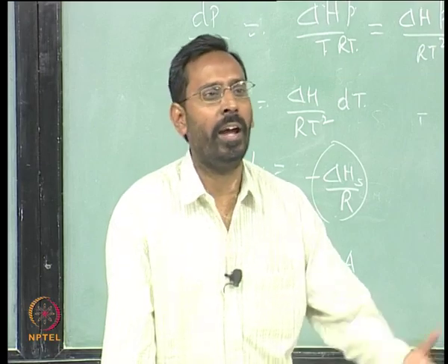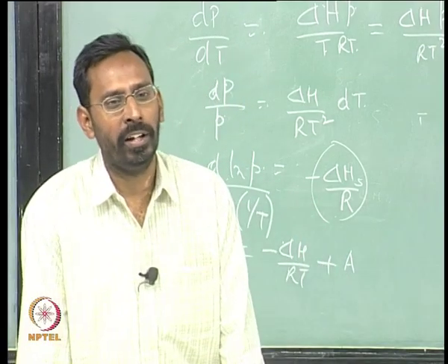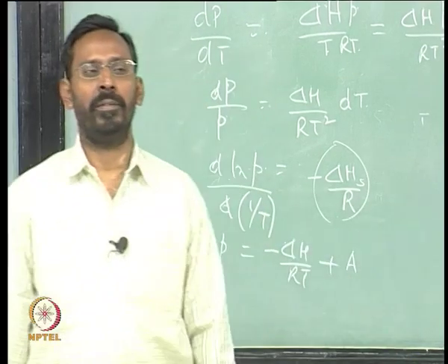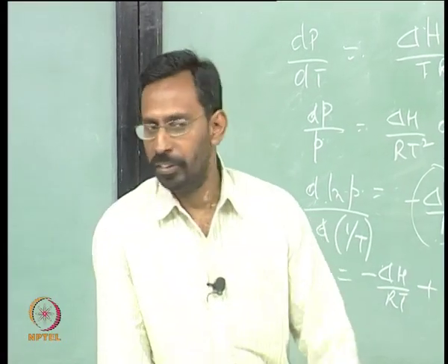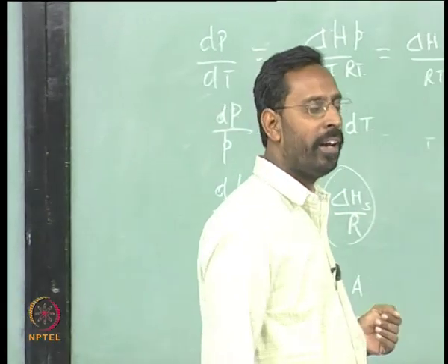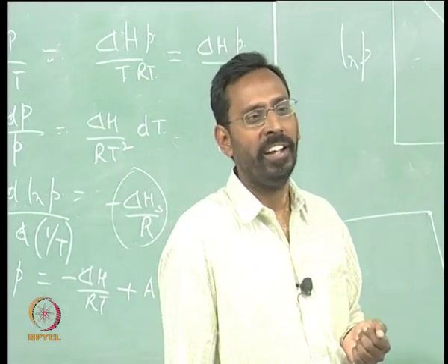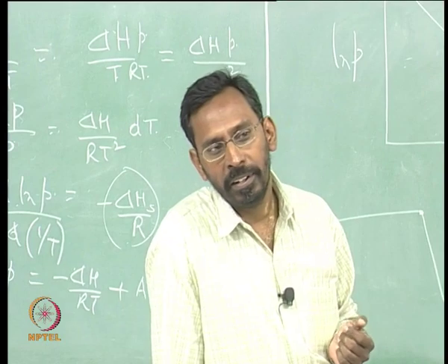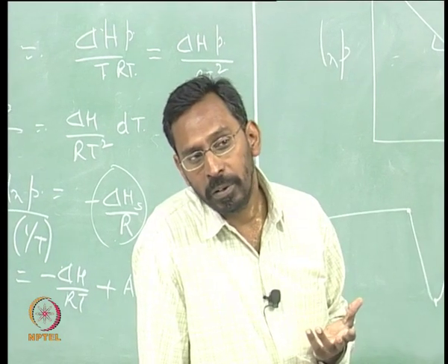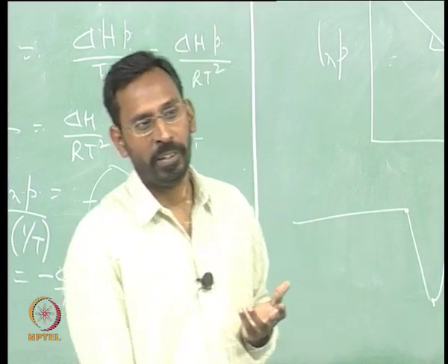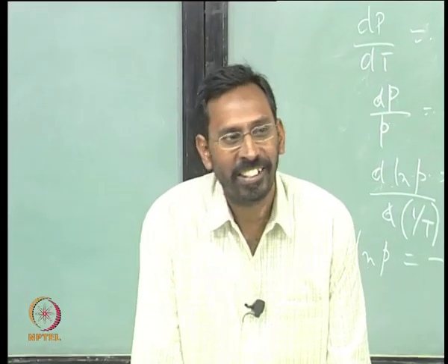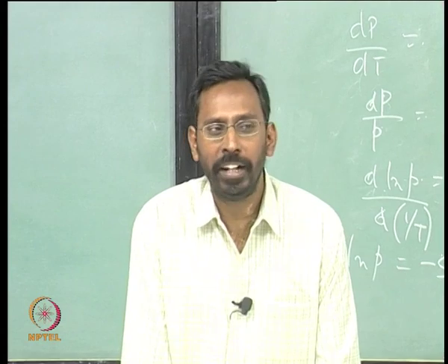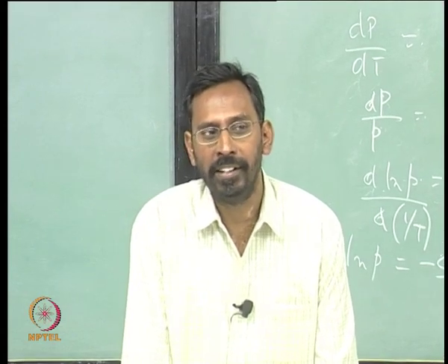Let us say I am melting a metal solid, I get a peak again similar, and there will be 3 temperatures there. Onset represents the beginning of the melting, then the maximum, the melting point, where the transformation is complete. Where it completes, that is the peak.